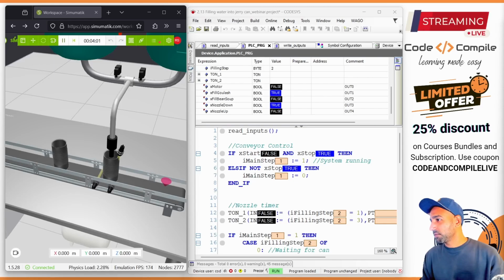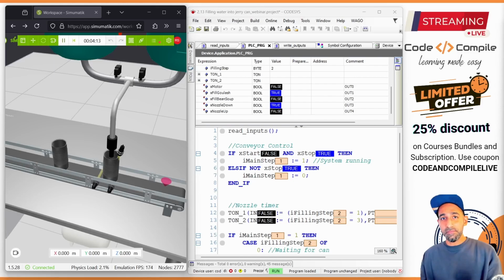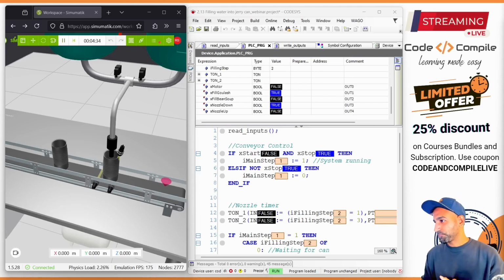Another question was, what can be done extra with CODESYS, which is not possible in SCL? So CODESYS has a lot of, I don't know the correct word for that, a lot of modules, a lot of plugins. So they have a lot of libraries, which SCL does not have. In TIA Portal, you also have your own libraries, but CODESYS has free libraries that you can use right away, and it's open to use. They have documentation. By libraries, I mean if you want to use CODESYS for, I don't know, EtherNet/IP or for IO-Link, or for Modbus. So there are libraries that you can use right away in CODESYS.